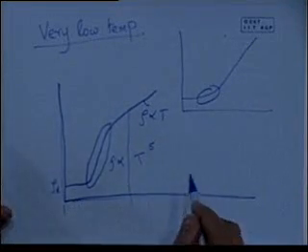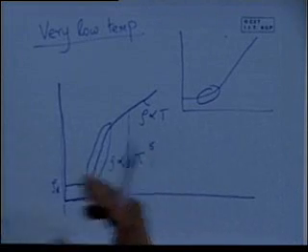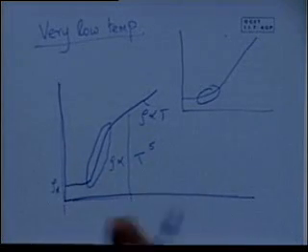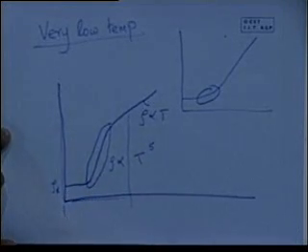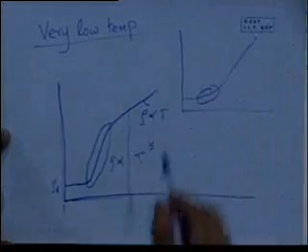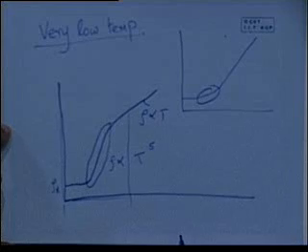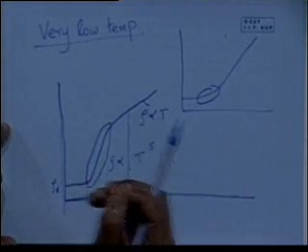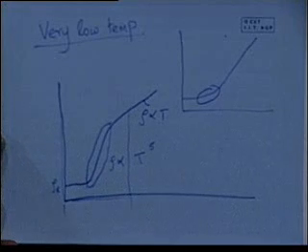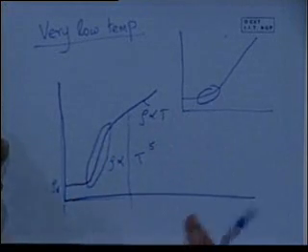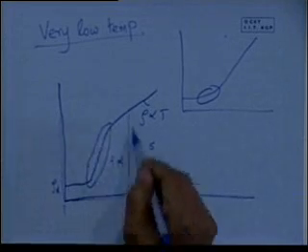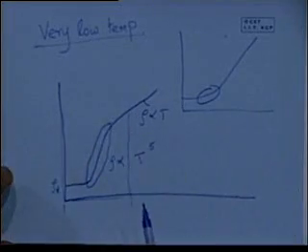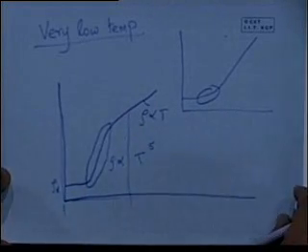And this is due to the fact that at very low temperatures, the atomic vibrations are more rapidly quenched. So as we come to very low temperatures, the influence of the temperature on the atomic vibrational amplitudes is far more significant than at the higher temperatures. Did you get that? Every time the temperature changes slightly, there is a very significant effect, a T to the power 5 effect, on the amplitude of vibrations, and therefore on the mean scattering time, and therefore on the mobility, and therefore on the resistivity. So at low temperatures, it doesn't follow that nice linear profile anymore. We have a sharp change here.